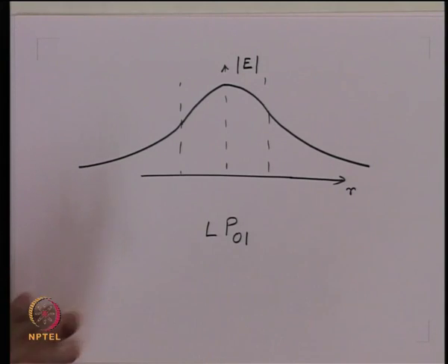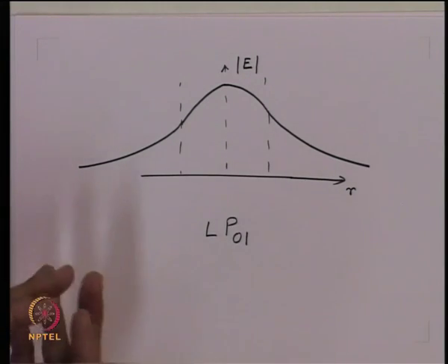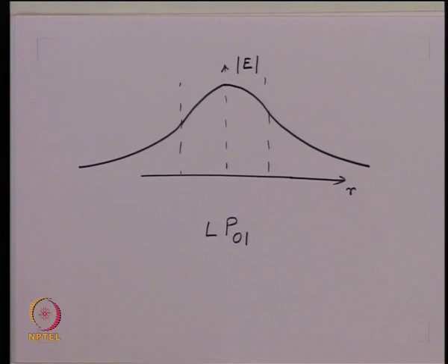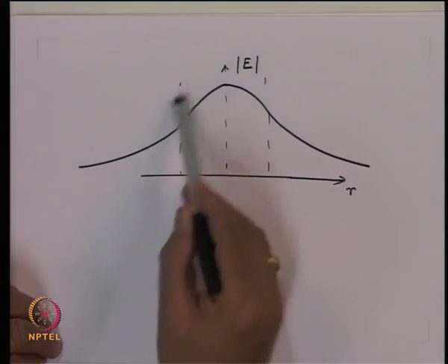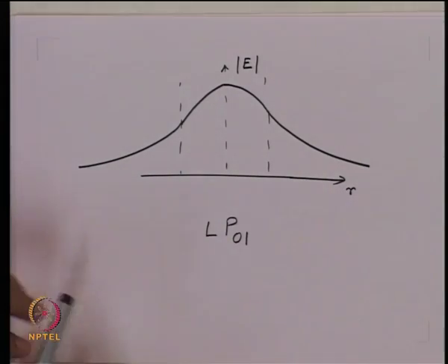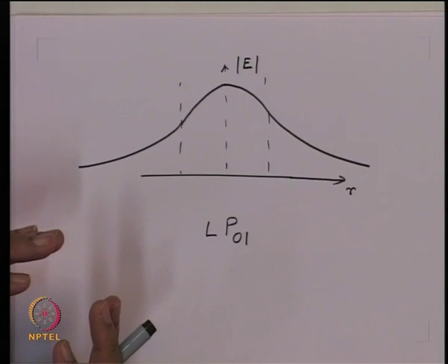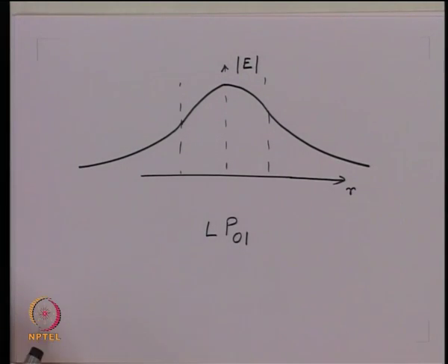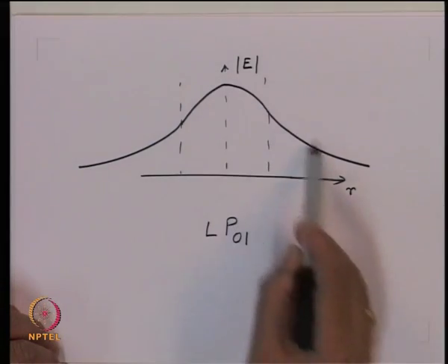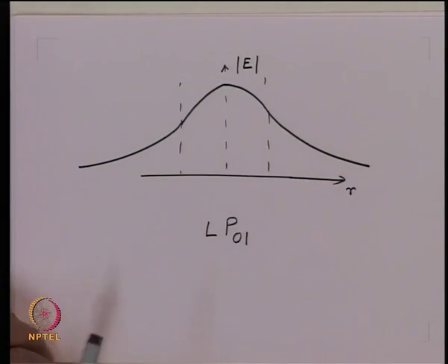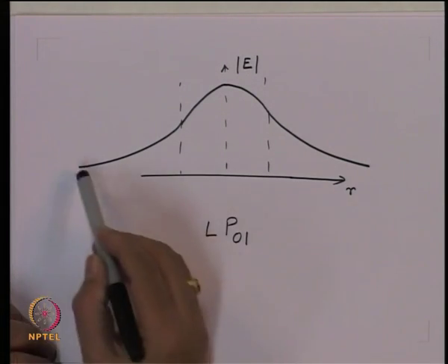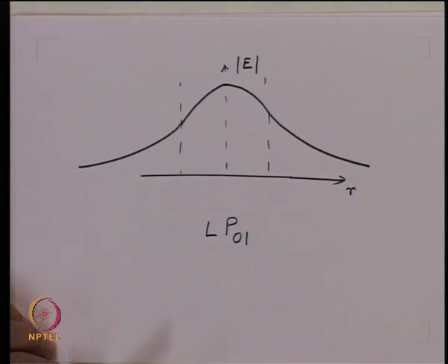And we also know that for a single mode optical fiber, the V number is very close to about 2.4. One can then show that this field distribution can be very closely approximated by a Gaussian distribution. So, within a few percent error, you can find the variation of this field; it can be approximated by the Gaussian distribution.